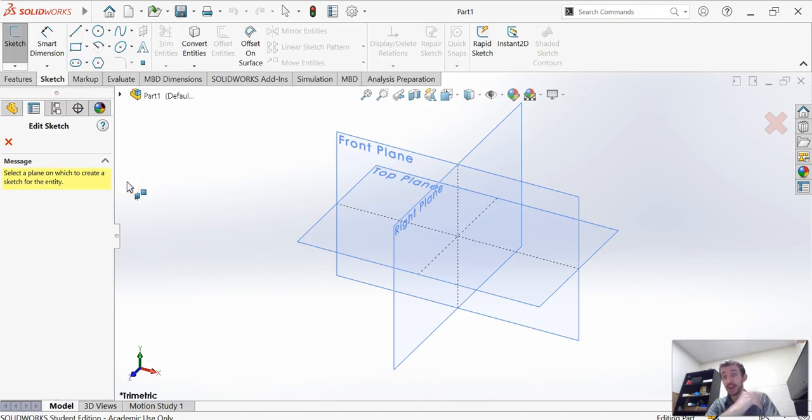Okay. Now I'm looking at this. What does front plane, top plane, right plane mean? It's how you look at the part. What shows you the most detail? Like once again, I have my water bottle here, okay? From the front, if you're just tracing it, it looks kind of like a rectangle. From the right side, like a rectangle. From, I'm going to pour the water out, there you go. From the bottom, or the top plane, it's a circle. So I can choose which one I want to start drawing on. I draw what I see. So I'm going to pick the top plane right now and show you that.